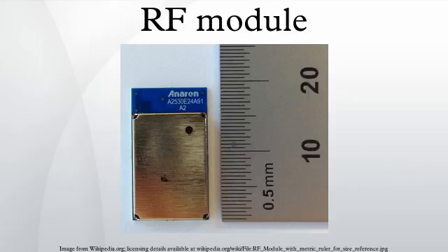The speed of the microcontroller interface depends on the speed of the underlying RF protocol used. Higher speed RF protocols such as Wi-Fi require a high-speed serial interface such as USB, whereas protocols with a slower data rate such as Bluetooth Low Energy may use a UART interface.